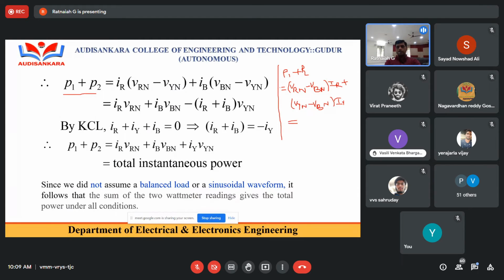So if we simplify this one, VRN into IR minus VBN into IR. Similarly, VYN into IY minus VBN into IY. So we already know that by applying KCL, IR plus IY plus IB is equal to 0, because at the neutral point, the three currents sum to 0.